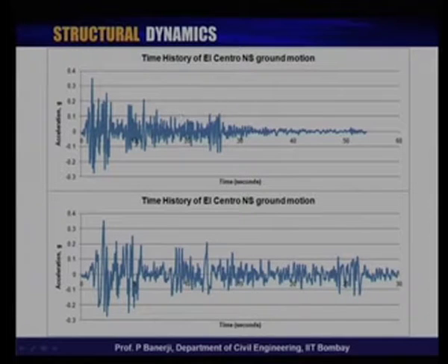So, this same thing, just this part has been zoomed up, and it gives you a better idea of how the shaking occurs. Okay. So, it starts, then it builds up, and then you get the peak. The peak ground motion in this particular case was 34% of g, which basically means 3.4 meters per second squared was the approximate ground motion that you had. And the peak ground motion happened about 2.5 seconds into the motion.